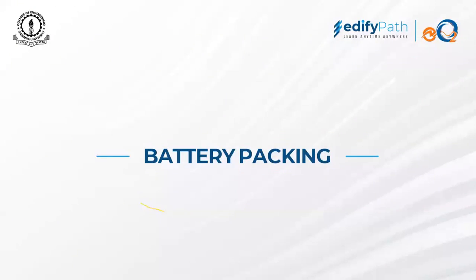So, battery packing. We discussed that the smallest units are the cells. We assemble the cells, connect them in parallel, and form the modules, and those modules are then connected in series. Along with the BMS, we achieve the battery pack. So cells, then modules, and then the battery pack.